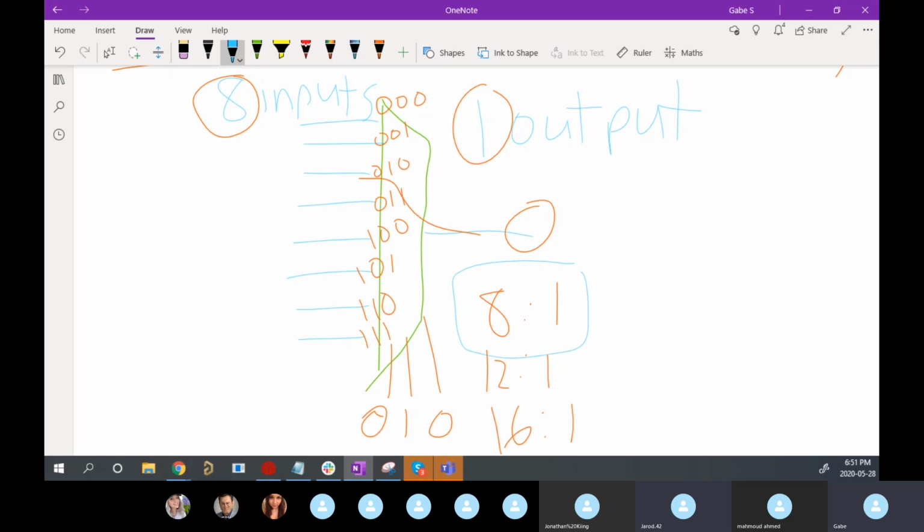And so what that allows us to do is instead of needing an ADC, for example, in this small case, that had to have 8 channels and measure every single one of these, we only need 1 channel now. Just with 1 channel, we can measure all of these 8 inputs because we go through the mux. And as long as we're smart about how we select which one is going through, we can read all 8 whenever we need to.